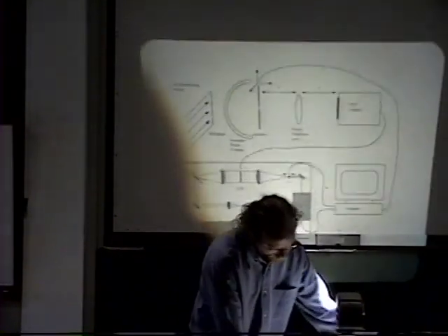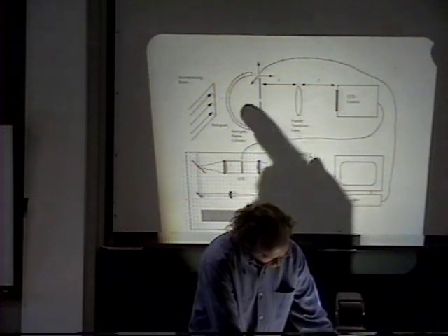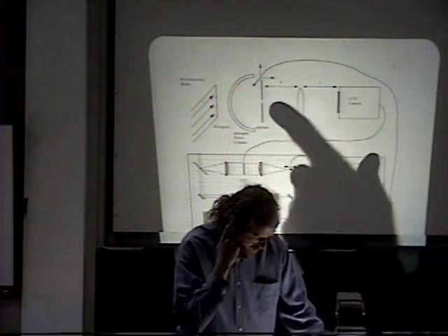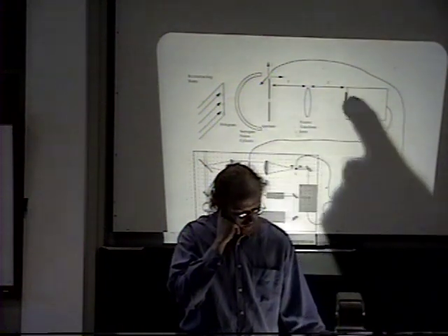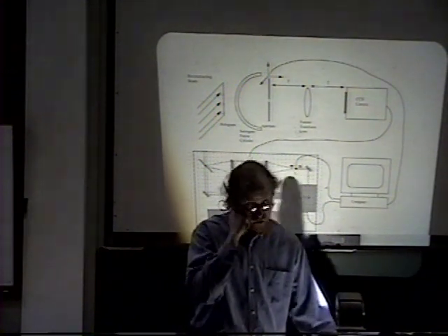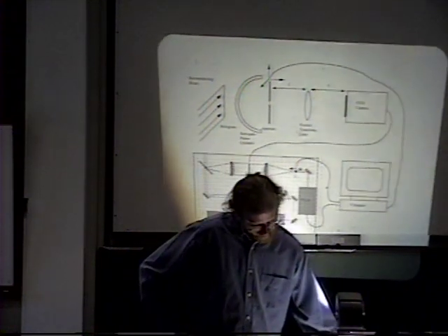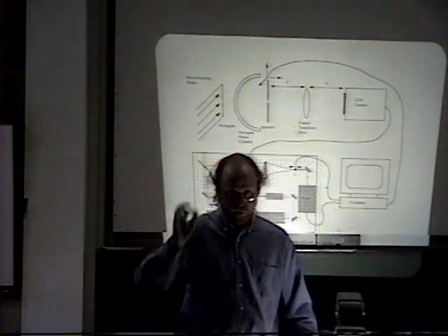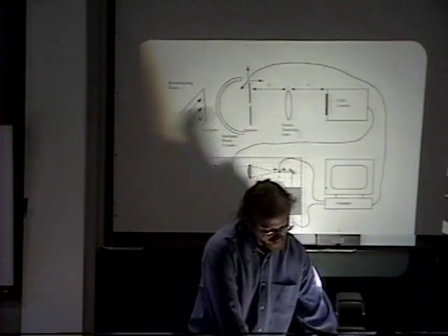When we do that, the whole system looks like this. We have our hologram in a pinhole, and for those of you familiar, this gives you effectively Young's fringes in the far field from the pinhole. Those fringes are then projected onto a CCD camera, which goes to an optical processor that many of you saw today in the lab. Then we can traverse the pinhole around to different points in space and analyze different points wherever the pinhole happens to be. I think that's a lot simpler than the one that I showed at the University of Illinois.